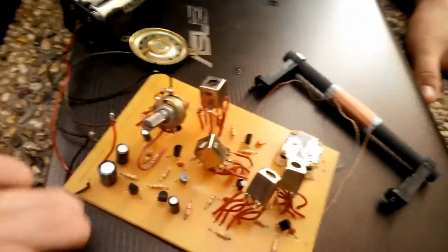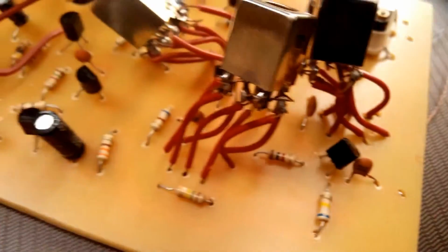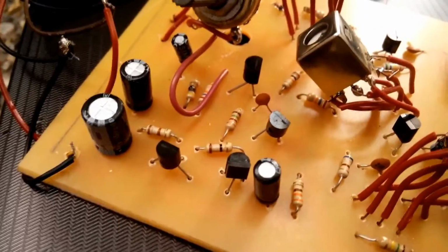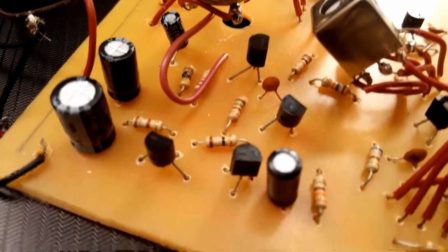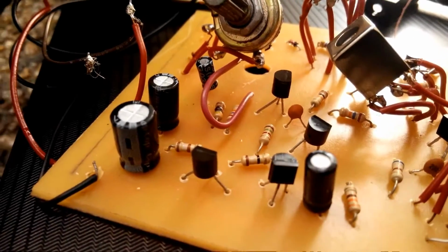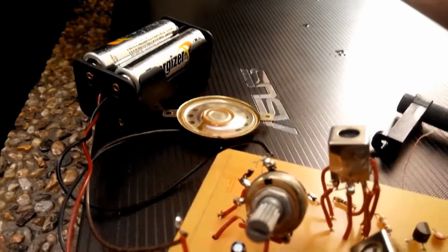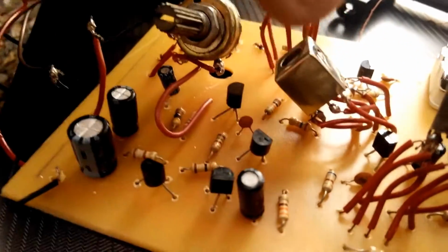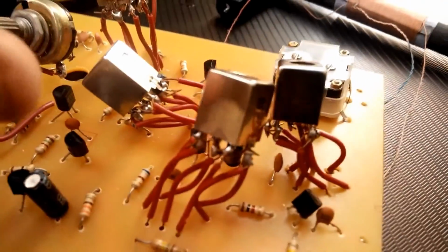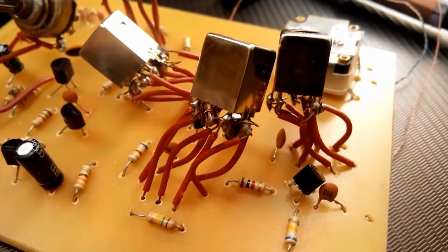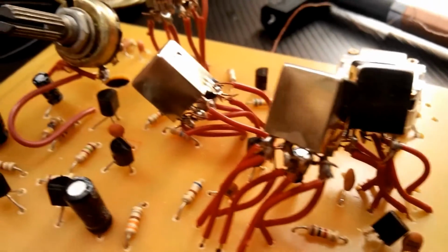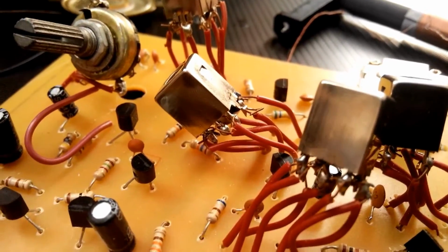One possible troubleshoot for that is that our transistors are not the recommended transistors for this type of circuit, but we acquired the closest thing to the specific transistors, and it may cause some non-linearity in receiving the signals, therefore allowing only noise to propagate in the speaker. Also, the added wires coming out of the IF filters are susceptible to additional noise signals, and therefore add to the noise we get from the speaker.